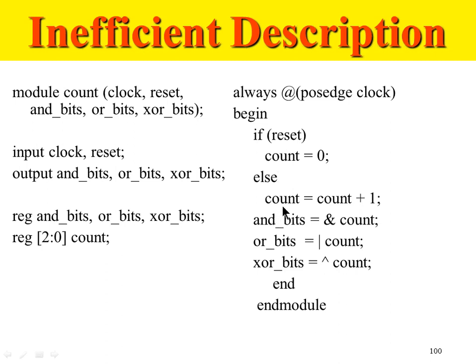And that is where the if-else-if statement ends. Since there is only a single line after the if, we don't need a begin and end. Same with the else. There is only a single line after the else, so there is no requirement for begin and end.